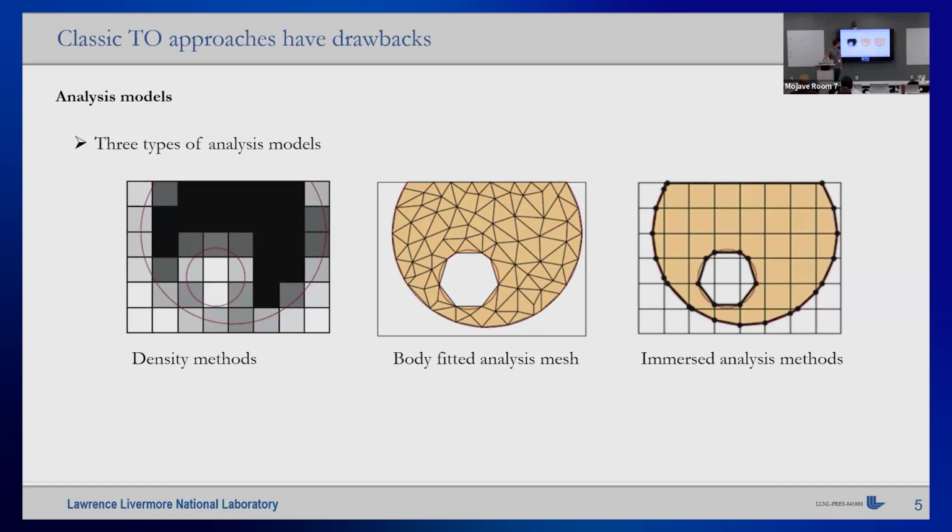The last one I want to point out is immersed methods. I think they are great for these applications. The problem is not every finite element code actually has this non-standard finite element implementation where we can solve these immersed problems. And even if we can solve them, they have their own issues, like basis functions with small support, which results in really bad conditioning, and we have to stabilize the stuff. So what we would like to have, and this was the point of this work, is a crisp geometry description, and then ideally a conformal mesh, which is easy to produce.